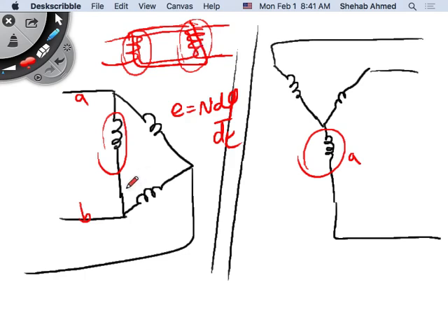Okay? That's why when I said, if this winding here, I drew it in parallel with this winding. So let's agree that if I draw them in parallel to each other, they will be on the same core. It's like they are on the same core physically. If they're on the same core, then they will have voltages that are in phase. Right? Can we agree to that? Yes. You mentioned something about it having a root-three difference of magnitude and 30 degrees. Forget about magnitude. I mean, this is the line voltage.